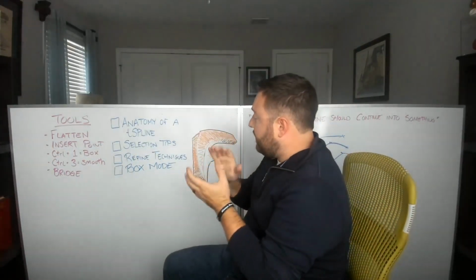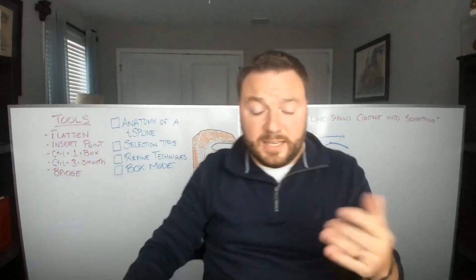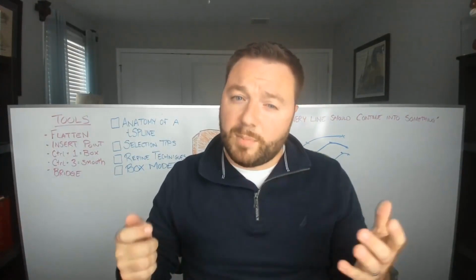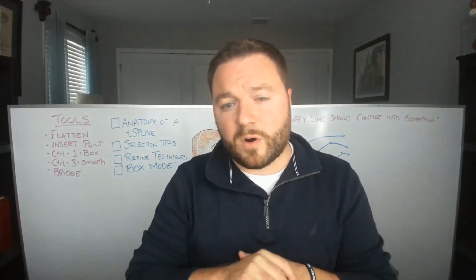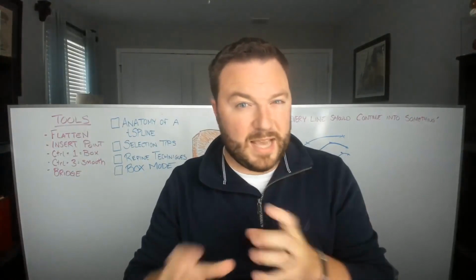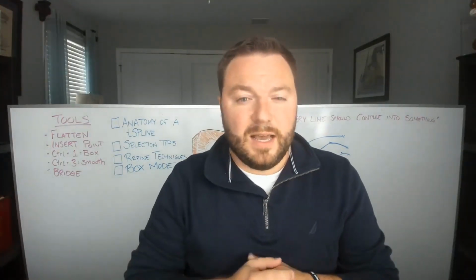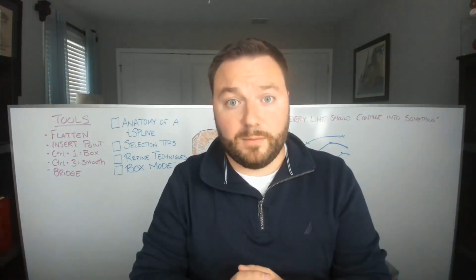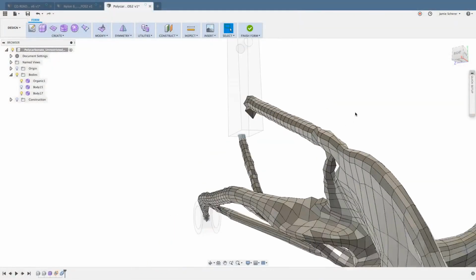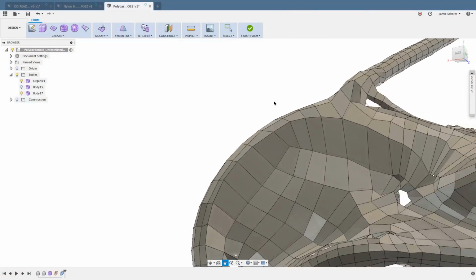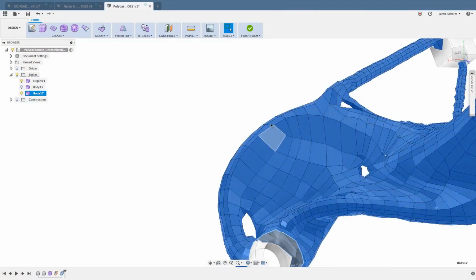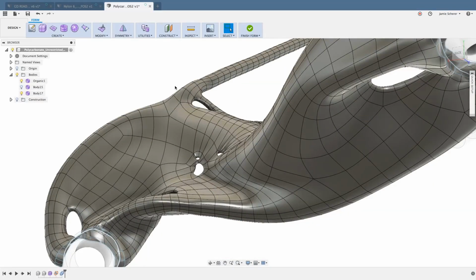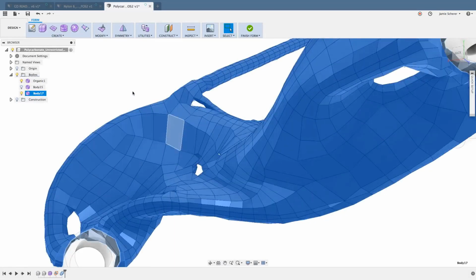The next thing I've been talking about is some different refinement techniques, I'll call them. I'm going to jump back into Fusion 360, and we'll go through a couple more examples, now focused a little more on working with holes. How do we patch and fill different holes, and what are the good, better, best techniques you can use depending on the result you're looking for? So let's jump back in. Let's first grab our object, and we're going to go back into smooth mode. The keyboard shortcuts, which I mentioned before: Control-1 for box mode, Control-3 for smooth mode.